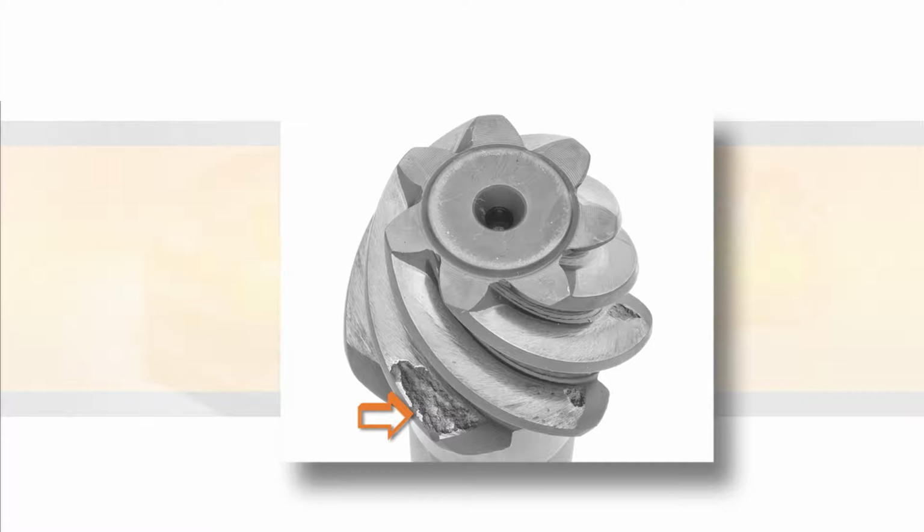You can see the damage created when axle components aren't properly lubricated. The faces of the ring gear teeth are badly worn. The damage on the input pinion is even more dramatic, with metal loss on the gear. Without lubricant protection, axle components wear out more quickly and will need to be repaired or replaced.